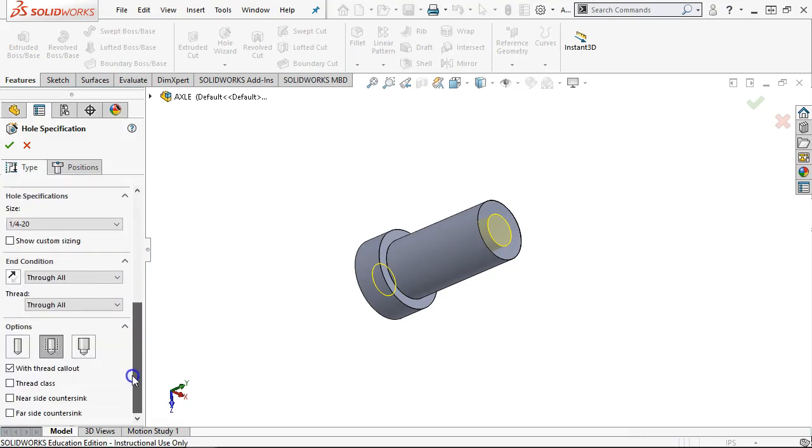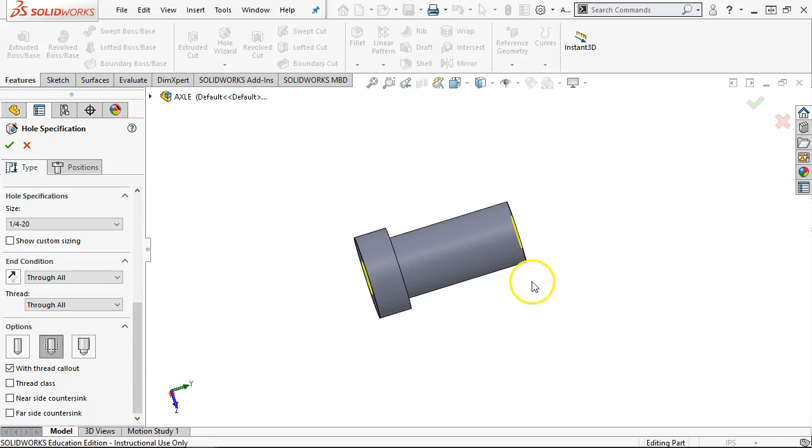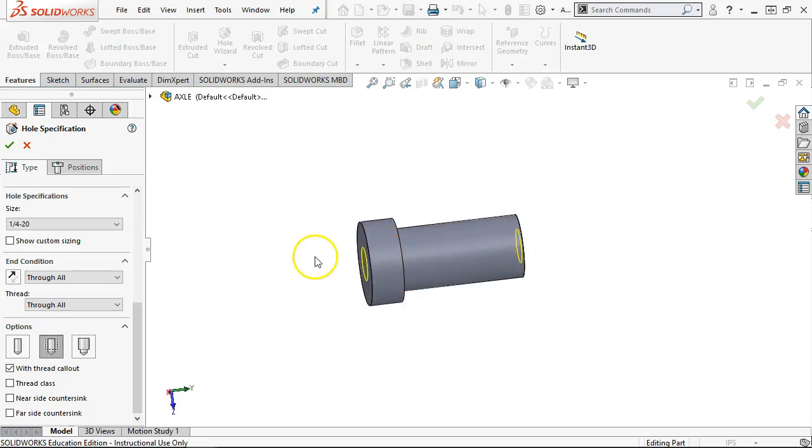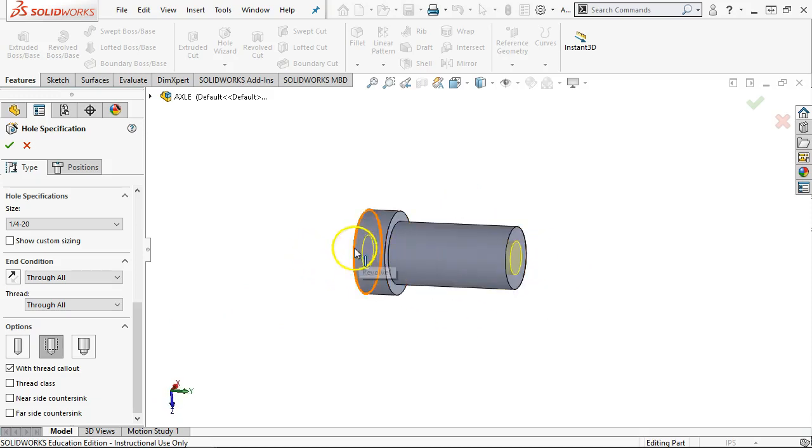And the hole can be through all. I still want to punch that hole through, mainly because with a blind hole this is going to be much easier to tap overall, especially if it's stainless and we pick a 303 or a 304. I really don't want to go to a 316. We're not at that level of needing corrosion resistance. If I drill this through 1 inch, that's a nice, easy nominal number, and I'll be able to blast that hole pretty quick.